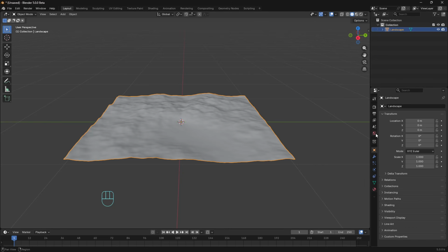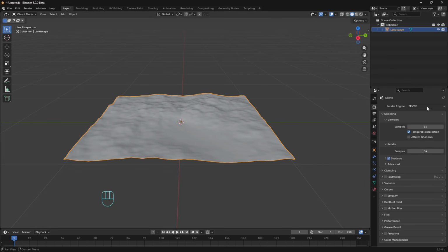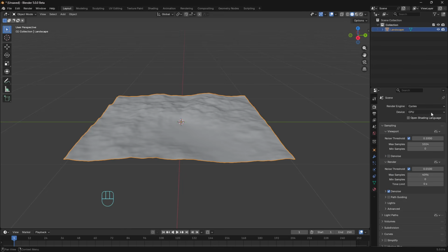Now I will set up nice render settings. I will go into Cycles with GPU Compute. I will enable the denoise here, and go to something like 100. It's enough to work with. For the rest, I don't touch anything. Maybe I will just put 512 for this one. It will be enough for this.